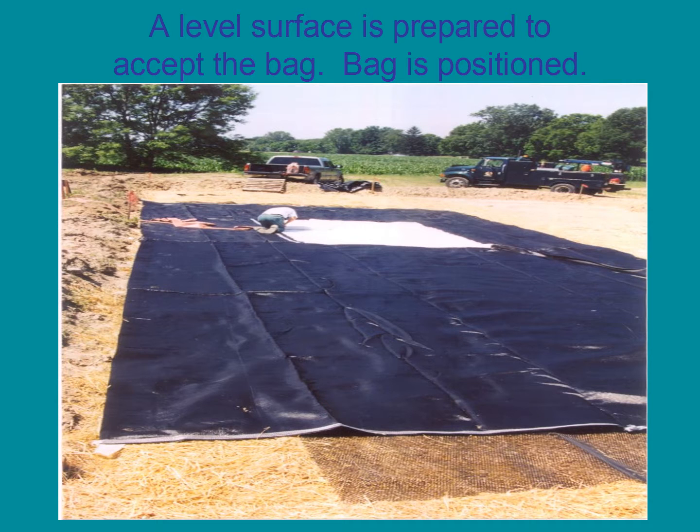It is important that the bag staging area be flat and well prepared. The bag must be laid out on a surface with no more than 1 or 2 degree slope.